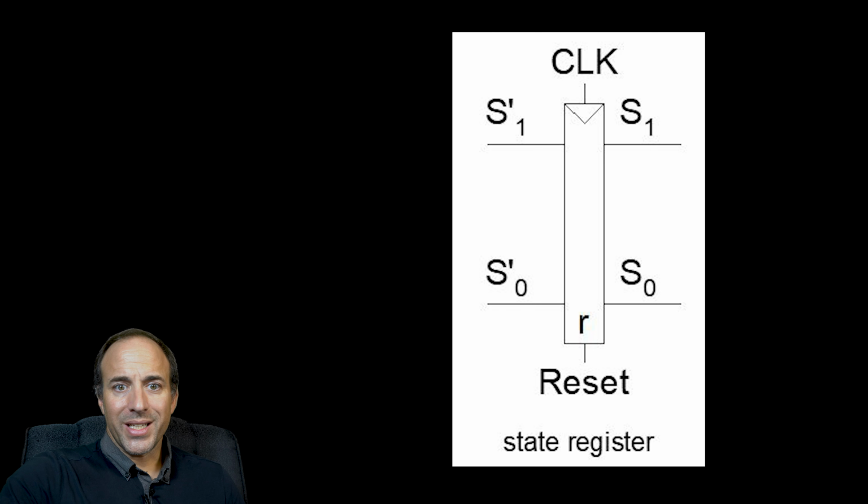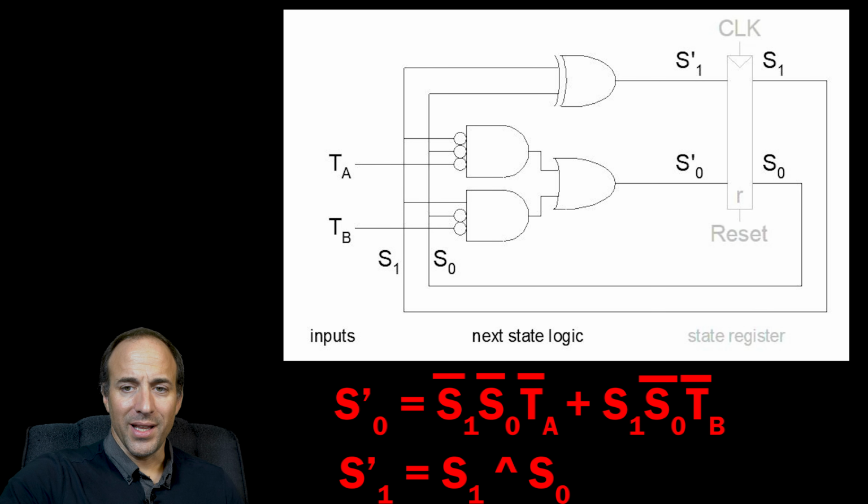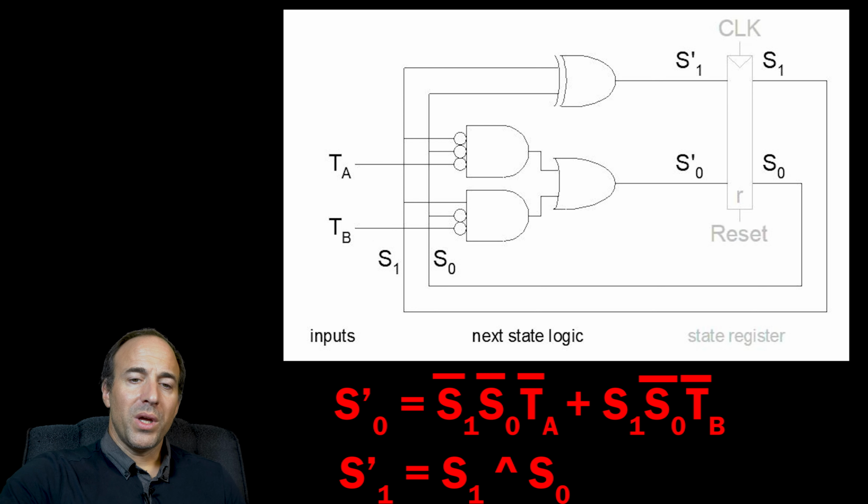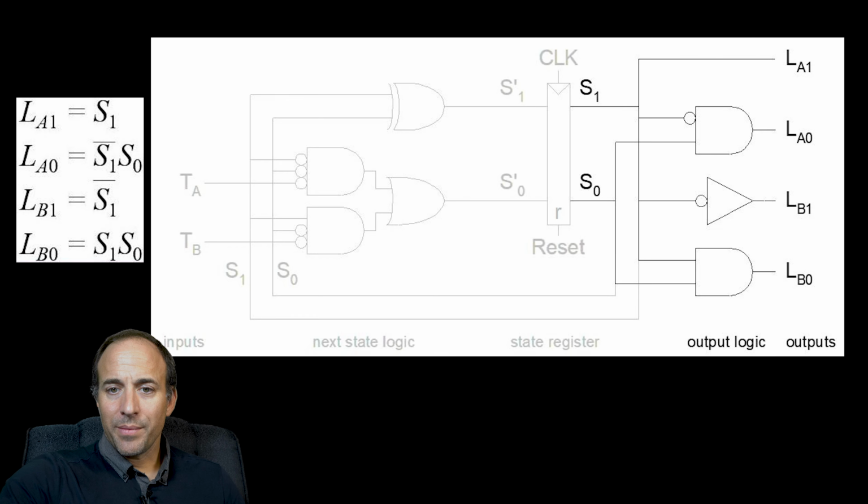We can now add the structure corresponding to the Boolean logic of the next state function, the next state logic. In this case, we can create a gate for each of the logic operators that we derived from the truth table. In this diagram, we'll use input bubbles to denote complemented inputs on any of the gates. We can then add our output logic, again associating one gate for every Boolean operator in the Boolean expression we derive from the output logic truth table.